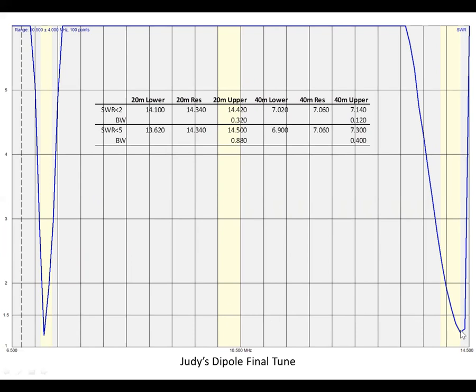And then the 20 meters adjusted, the length of the wire was adjusted so that I ended up here with this SWR plot like this. Now, one of the trade-offs with a trap antenna is that the lower frequency part of it, in this case the 40 meter band, has a much narrower bandwidth, which is the distance in frequency, say that it's below SWR 3, than the non-trap side, or in this case the 20 meters. We have a much wider range of frequencies on the 20 meter section of that antenna that is below 3 standing wave ratio.